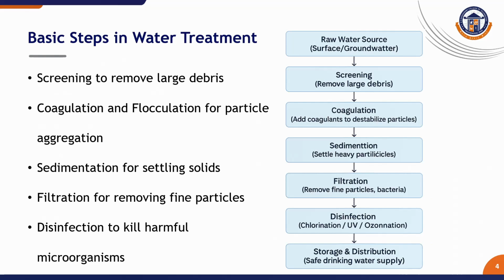In the filtration process, water passes through porous media to remove smaller particles and microorganisms. Next, the disinfection process, the final safeguard where chemical or physical methods are used to kill or inactivate the pathogens. Each step progressively polishes the water, ensuring that by the time it reaches the consumers, it is crystal clear and microbially safe.